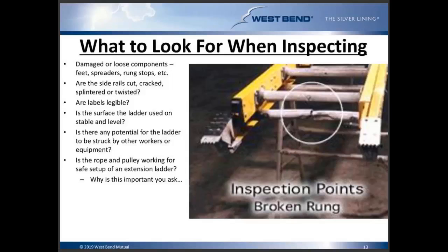Also for step ladders, making sure our spreader bars are in place as well. Rung stops: that they aren't missing or not engaging properly for our extension or non-self-supporting ladders.